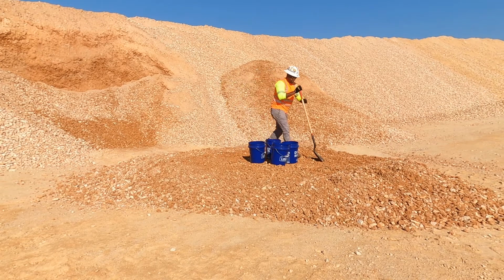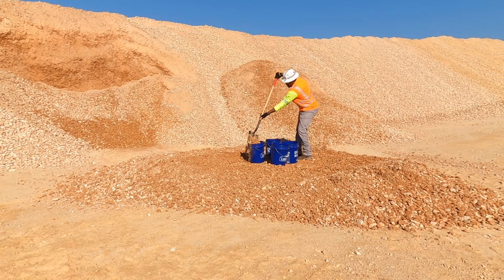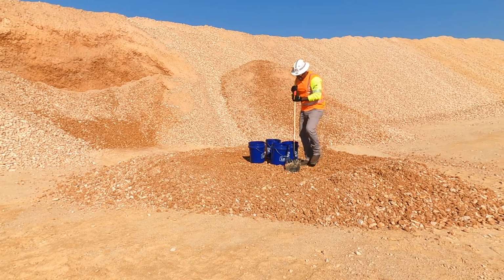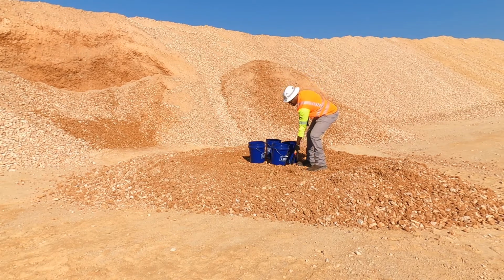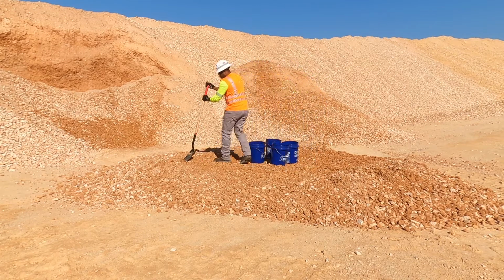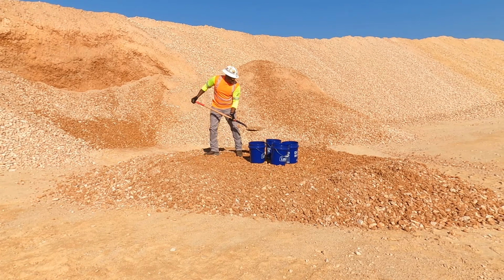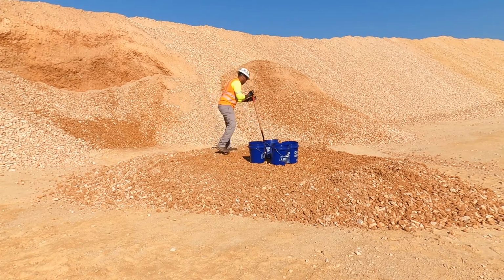Obtain additional shovelfuls from different quadrants of the sampling pad and in areas avoiding previous shovel holes. Remove material from each quadrant to fill one sample bag or container. Minimize loose material falling from the sides of the hole and loss of material from the shovel into the hole or adjacent ground while filling sample bags or containers.